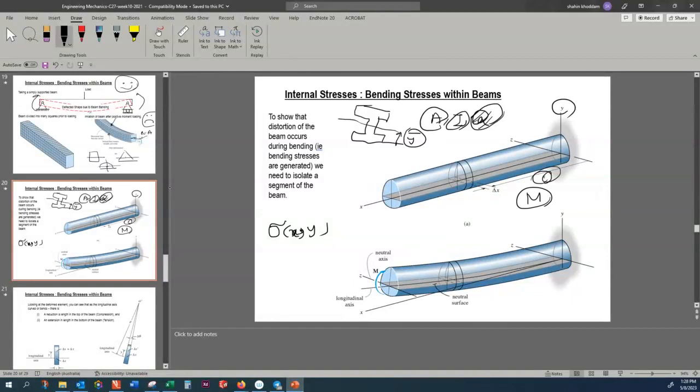That is not enough. You also have to find the variation in the Y direction to find out what sigma is maximum for the entire beam. The maximum normal stress is likely the point at which the crack would grow.